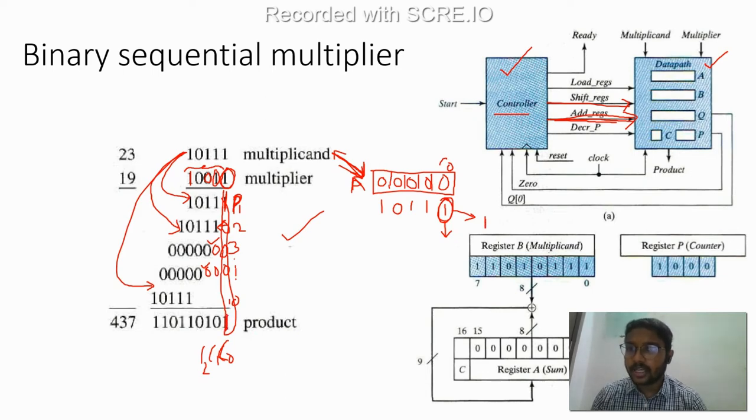Now again you check the next bit of the multiplier, and you right shift all these things. So this will go here, this will come here, 0 1 0, right? Now your multiplier bit is again 1, so you don't need to left shift the multiplicand here. In partial product 2, you were left shifting the multiplicand, but now it's not required, because the relative positions are matched.